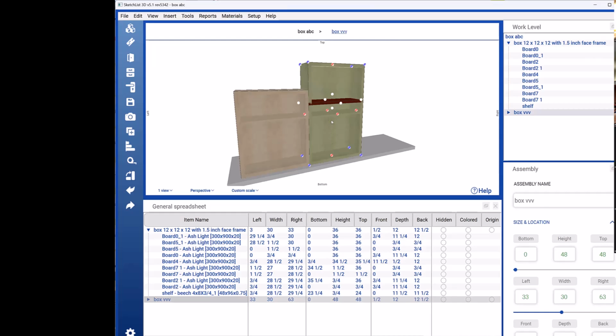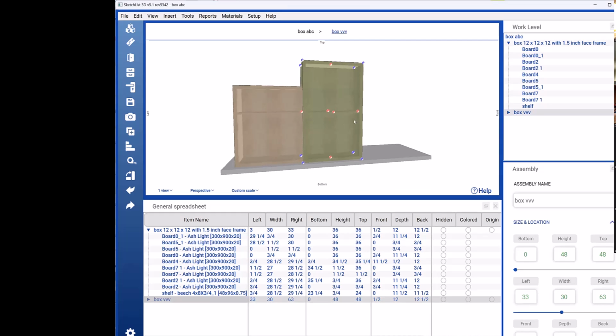Don't touch it. If something is cut by the slice plane, then we're going to add, in this case I think it was 12 inches, add 12 inches to the height. The first time I did it, the slice was below the shelf and it got pushed up by the 12 inches, which we didn't want. So I redid it, no big deal, and that's that. So now those are the same height, like that.